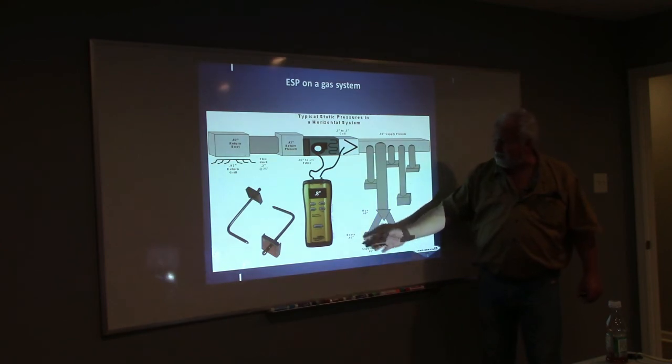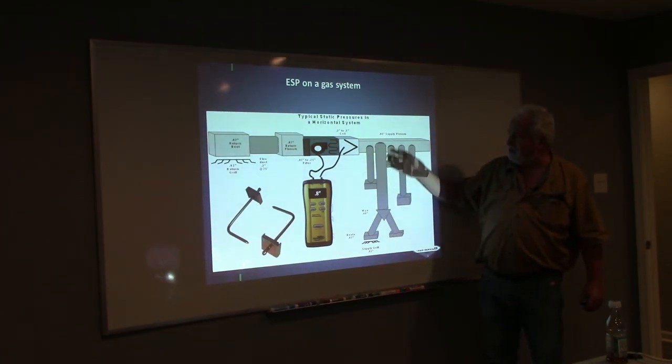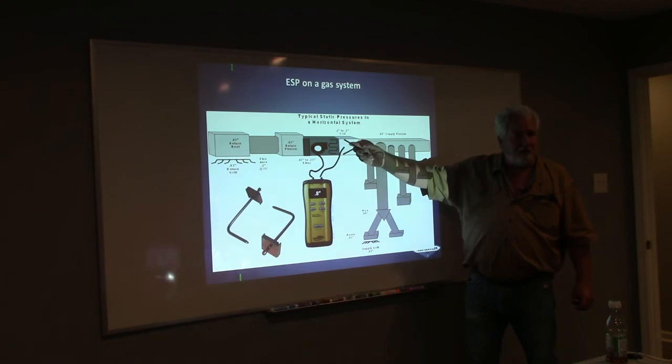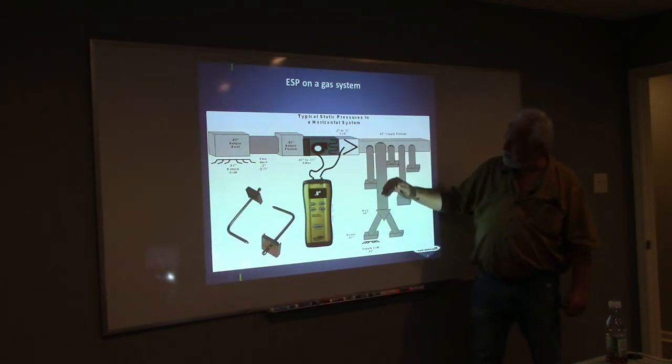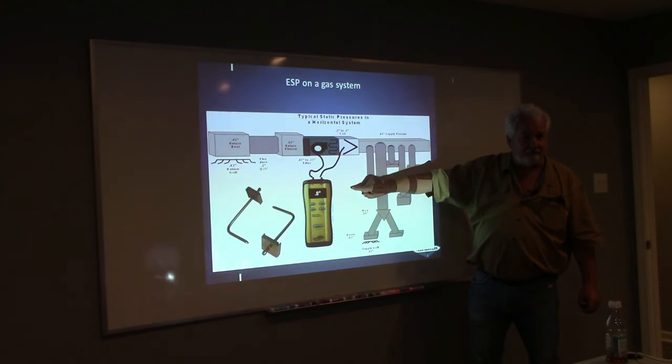If I add that to the 0.02 for the boot, 0.08 for the Y, whatever for the ductwork itself, I do have some resistance in the plenum as well. Is that right? Do I have resistance in that coil? Good. Resistance in the coil, resistance in the plenum, resistance in the duct, all of these add up to the supply static pressure.